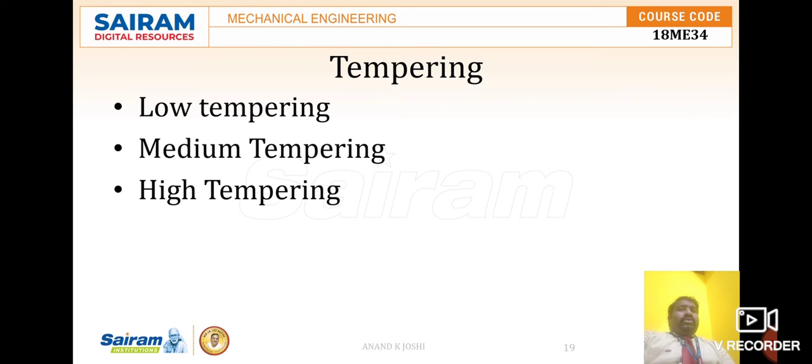When it comes to medium temperature tempering, the temperature range is from 250 degrees centigrade to 450 degrees centigrade. The hardness and strength of the steel decrease, while ductility, that is the percentage of elongation, increases. This results in a fine pearlite structure which we call troostite. Troostite has less brittle properties and is applied to components such as coil springs, laminated springs, beams, axles, and even the chassis.